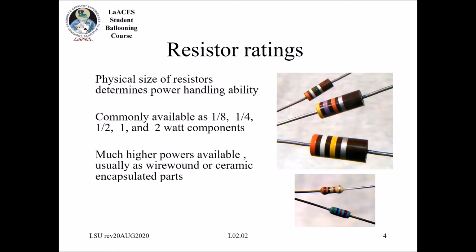And then you can take that and multiply times your current, or use one of those other forms of the power laws that we were talking about, and you can get what power is going to be taken on by your resistor. And with that, you need to make sure you pick the right resistor for the power that is going to be running through it, or else it will burn up or some other failure mode that we really don't want to deal with.